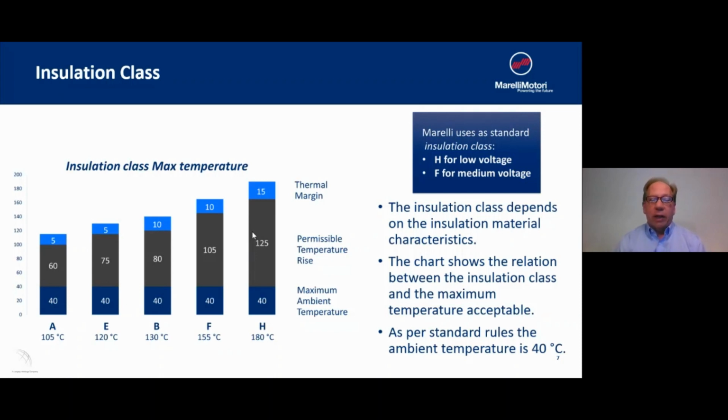This means that the insulation of the generator can handle this degree of heat without breaking down. And so when you're comparing one generator to another, comparing bids, and you want to make sure you're comparing apples to apples, make sure that both units have the same insulation class. The insulation class determines how much material is going in, which also factors into the cost to manufacture the generator.